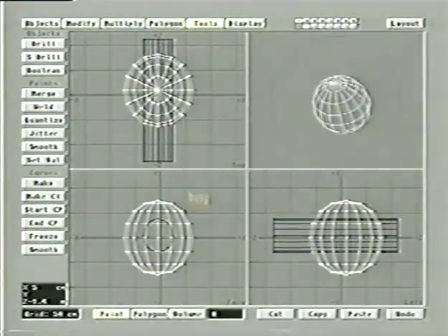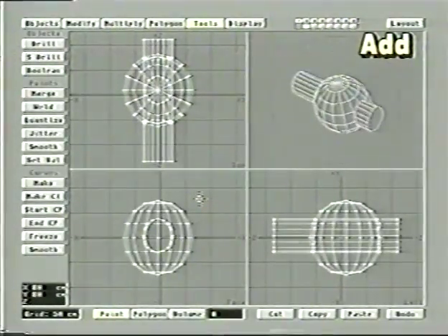And what add will do is it actually combines both of them, but it does not remove any polygons. Now, for this reason, add's the one that I tend to use the most. Union, particularly, can be very, very handy. Also, intersect can sometimes be very helpful. Union, I find I end up using a lot to sort of fuse objects together, and you'll see a use for that a little bit later.